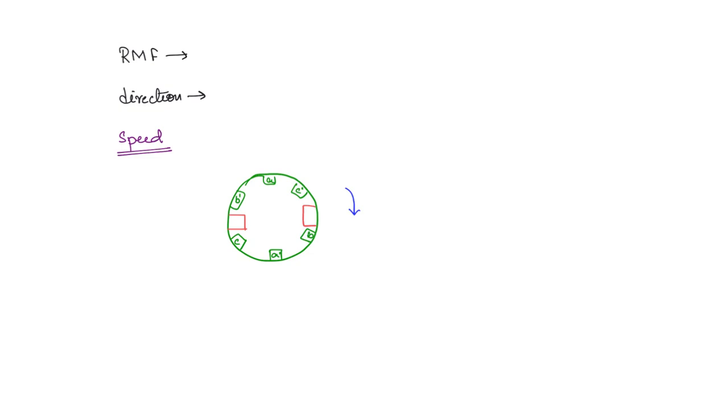So which one will form the north and south pole here? If you're taking a particular instant of time, okay, so we got 1.5 hm angle 90 minus omega t, okay. So now this position that we have, it is either 0 degrees or 180 degrees. So if you take 0 degrees, when will this phase be 0? When omega t is equal to 90 degrees, or you can say pi by 2 radians. So at t is equal to pi by 2, what will be the direction? This will be the direction of magnetic field.